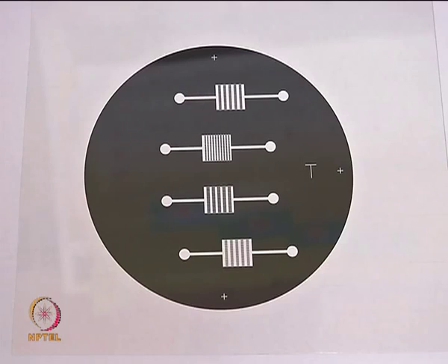Okay. As I was telling you, we first study the device structure that we want to fabricate, and then we come up with the mask layout, and we get the mask printed that you can see here. Okay, and this mask is used to follow the photolithography process to make a master, which we will be using to make the PDMS based microfluidic device.